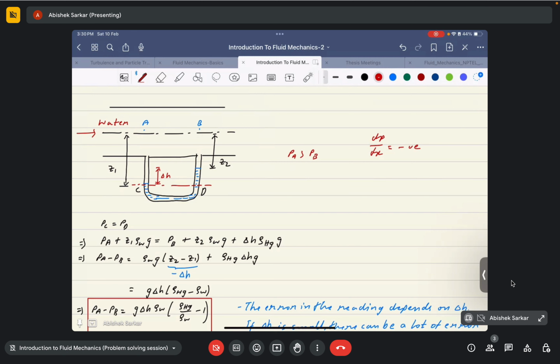Because as the distance is increasing, the pressure is decreasing, so the gradient is negative. And you will see that this is one of the very fundamental factors that drives the flow in pipes. This negative pressure gradient is one of the fundamental driving forces in the case of flow through pipes. So that's just a thing to remember, so that you are able to correlate when we discuss flow through pipes thoroughly.